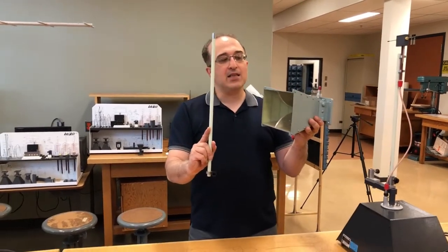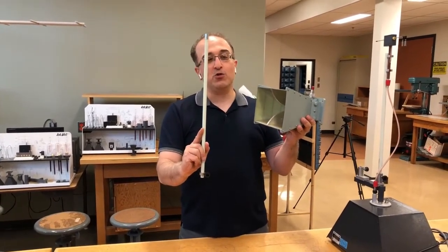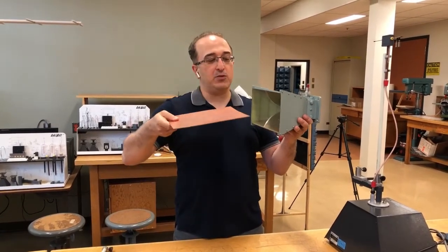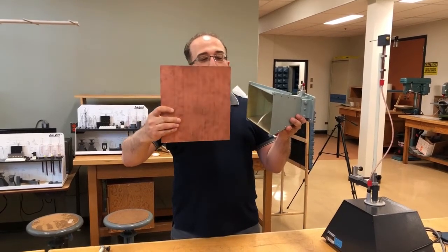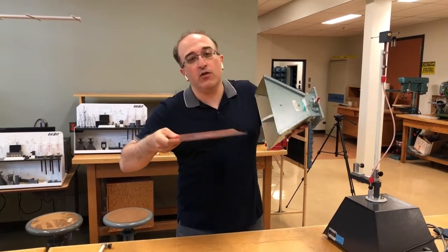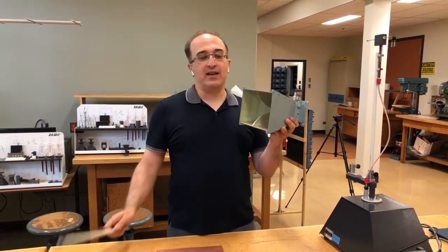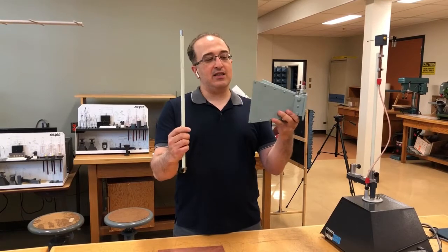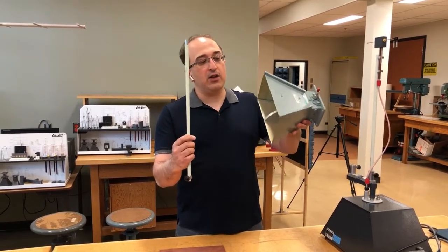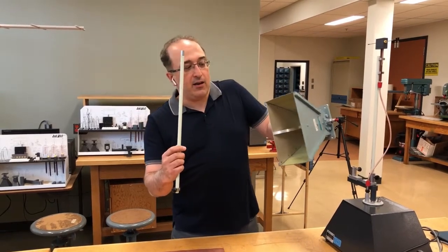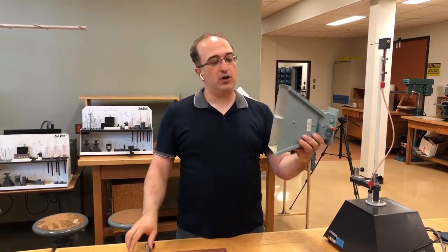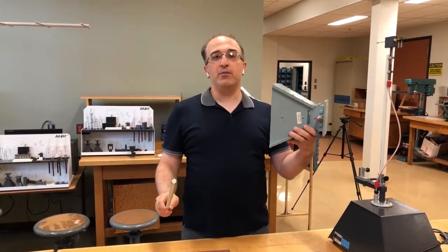Now, the next step would be I want to go to the E-plane. If you remember again, this is now our H-plane, so if I want to go to the E-plane, this is my E-plane. To perform the E-plane measurement, I need to rotate the whole thing, right? So let's go back again. This was our last measurement. We did H-plane, co-pole. So what we do is rotate this one 90 degrees. And now we're going to perform the measurement like this. Let me change my hand. We're going to rotate it like this to perform the E-plane measurement.